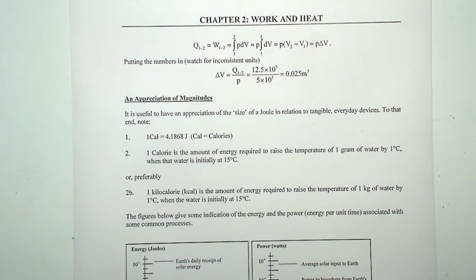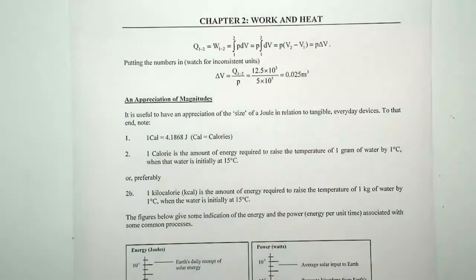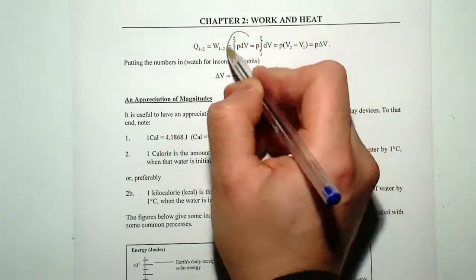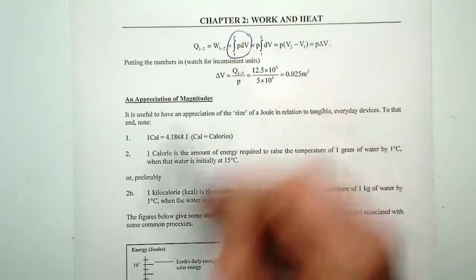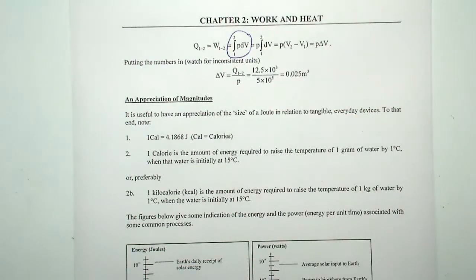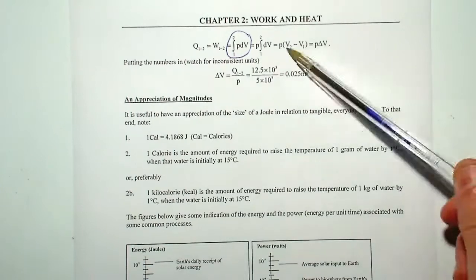Because the right-hand side of the equation is 0, since there's no change of internal energy, I can simply move the work from the left-hand side to the right-hand side and say Q is equal to W. I don't have any equation for Q for now, but because this is displacement work, this equation applies here for work: the integral of P dV, which we've seen a lot of times. We know that the pressure is constant. The problem says that pressure is maintained at 5 bar, therefore P can come out, and the integral simplifies to V2 minus V1.